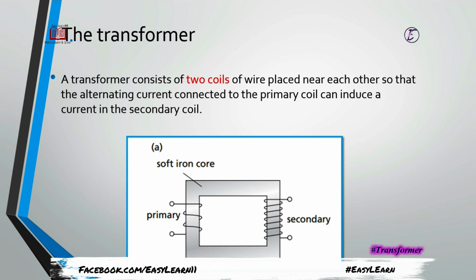This is the basic diagram of the internal working principle of the transformer. Suppose that there is a soft iron core. We basically use it for the transfer of the magnetic field lines that are generated due to the primary coil. The primary coil is mounted on one arm of the soft iron core, and the secondary is on the other arm of this iron core.